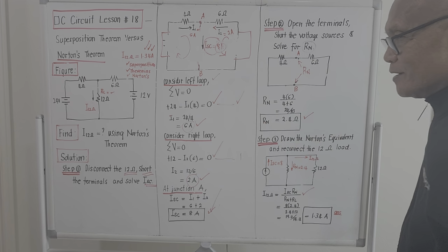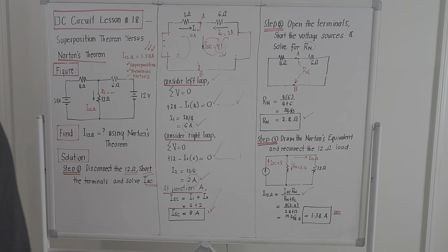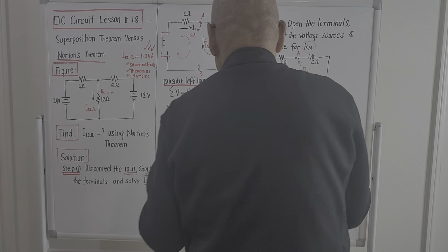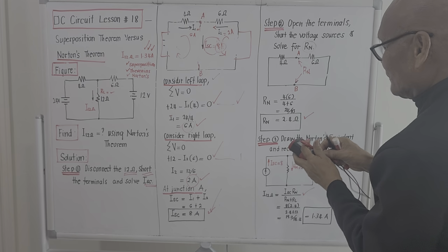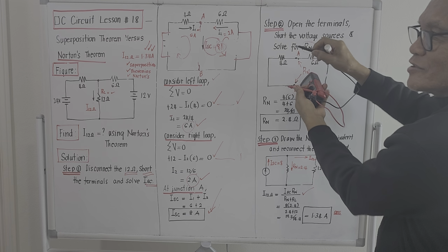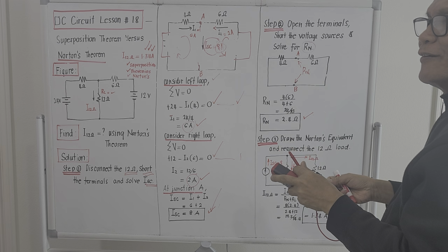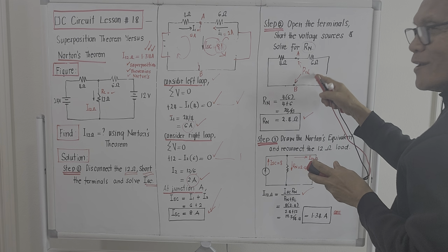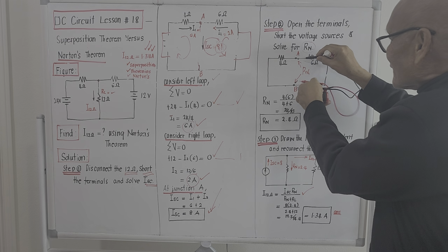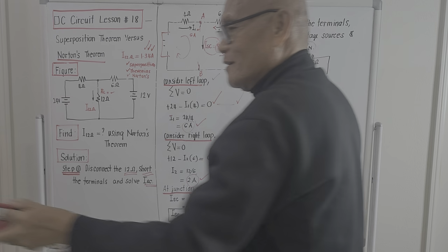We open it. We use our tester to compute for it. It seems we are having a multi-tester, then we'll place it here. Okay? That's in the actual thing, but theoretically, if we are solving on the board, what will be the value of R sub n? But in actuality, you just get your voltmeter and place it here after shorting the voltage source.